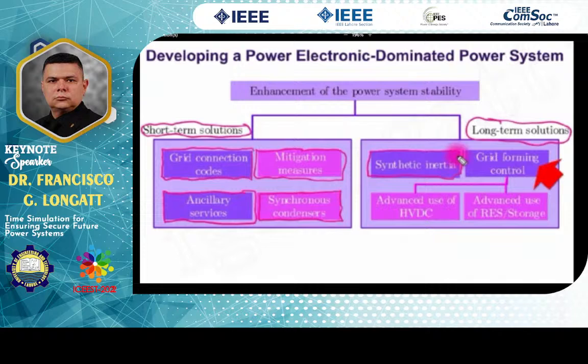For that reason, this synthetic inertia, or digital inertia, or emulated inertia, there are many names in the market, many flavors of this kind of, let's say, controller. Synthetic inertia has the limitation that it requires the value of the gain on that controller to be very carefully specified.